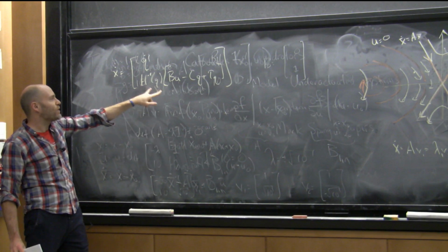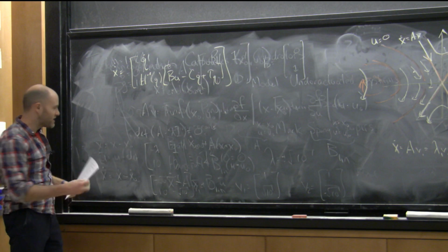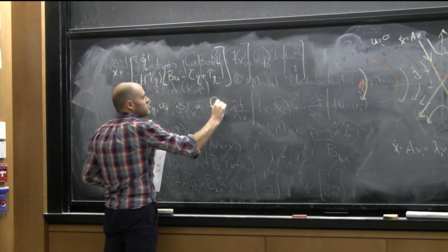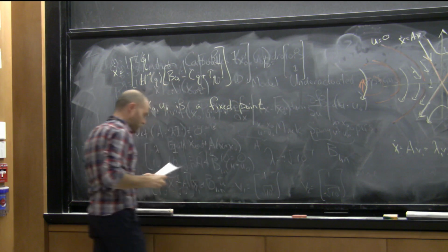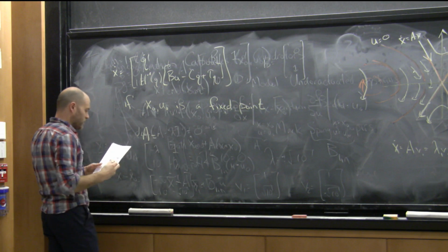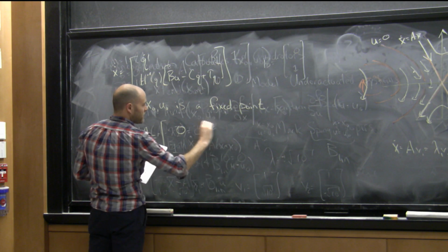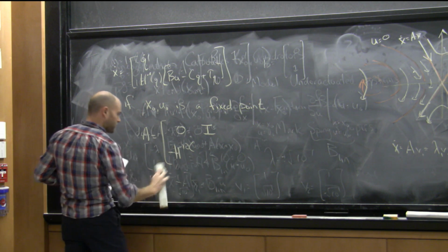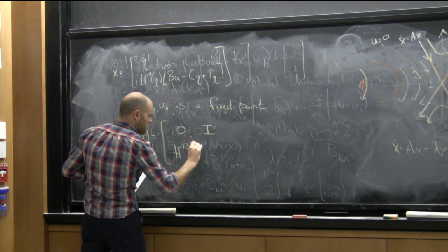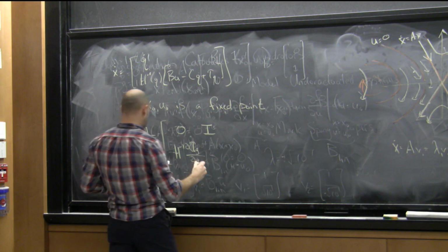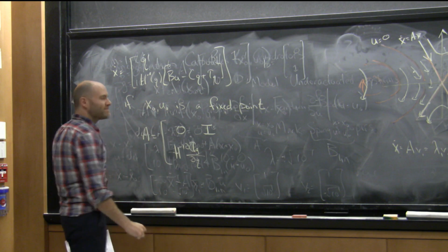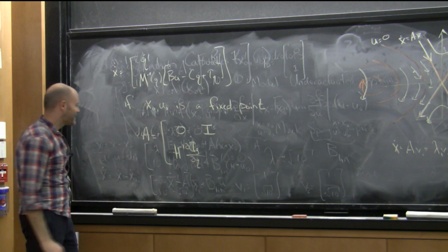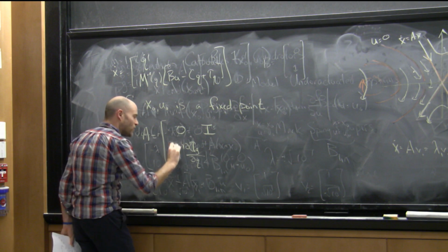The terms that involve H inverse always have to drop away in the linearization. So magically through cancellation, if you're linearizing around a fixed point, then the whole thing reduces to a block matrix form, where the only terms that exist are 0, H inverse partial tau G, and so on. I changed my notation this year, and I keep writing H, and I'm trying to write M. I apologize. If you ever see me write H, yell at me. And I just realized I had to change my sign because I changed my sign on my gravity vector too. Old habits die hard.